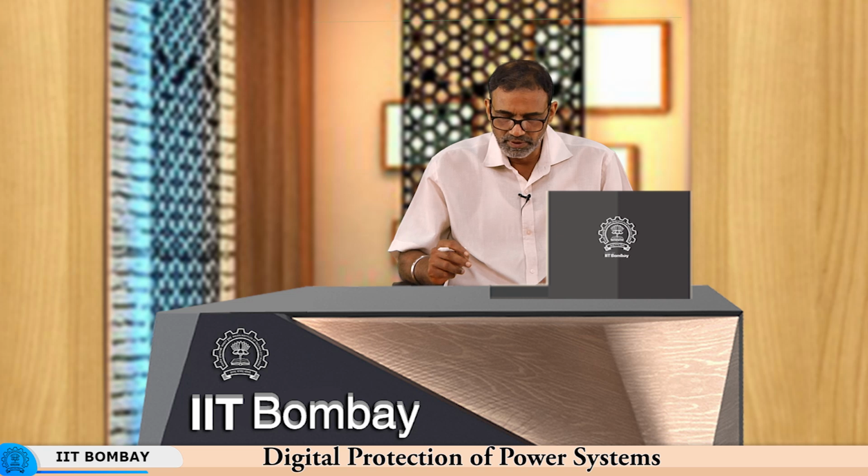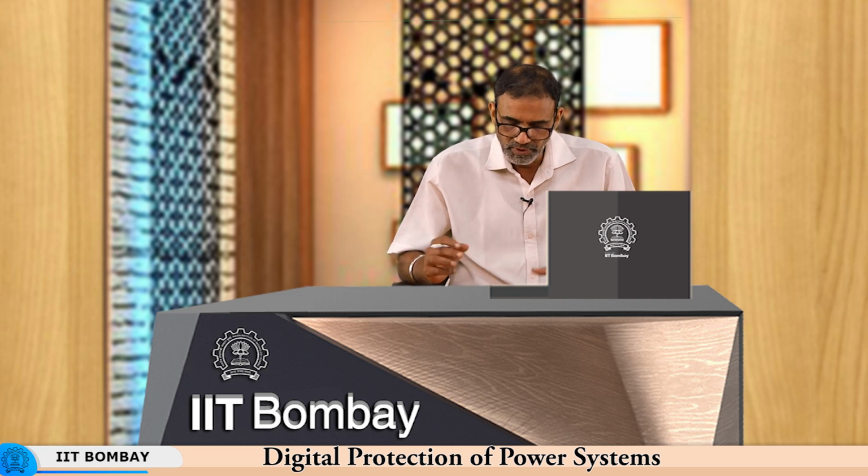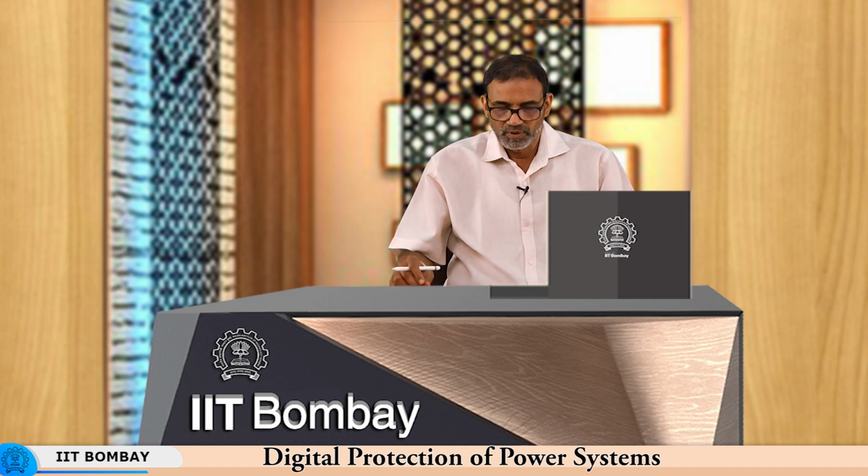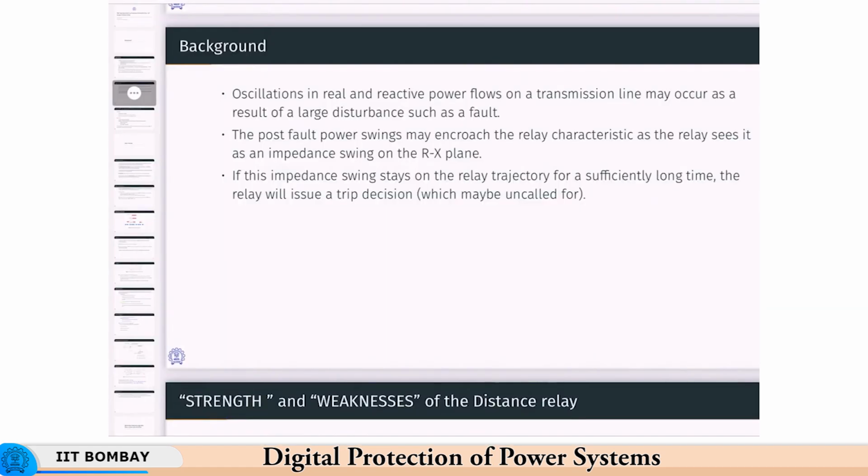Okay, because that is the only input that is available to the relay, that impedance. It sees that apparent impedance, that is why we call it a distance relay. So, if the impedance swing stays in the relay trajectory for a sufficiently long time, the relay will issue a trip decision.